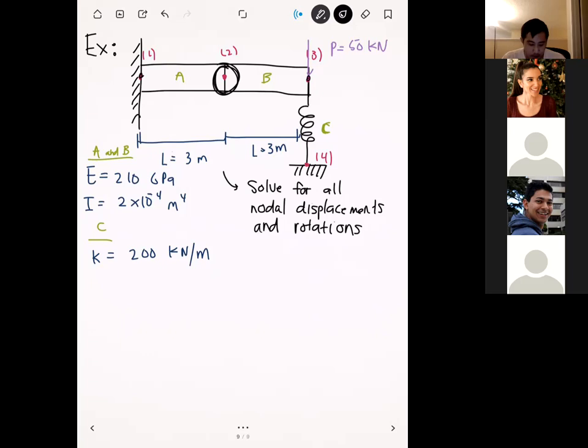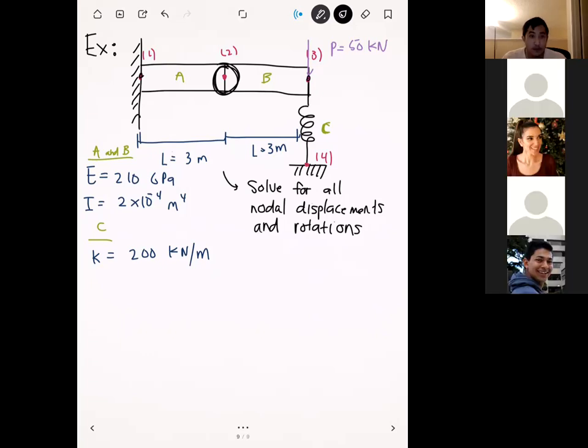Gotcha. Yeah. Thank you. If we cut both the elements in half, would that just be more accurate? Yep. Actually, that's my next point too. Cutting it just once is arbitrary, right? But if you want more spatial resolution, you can keep cutting this beam up, just like that, and you can make like a nice candy necklace or something like that. But just remember that every time you cut the beam in half, that's one more element stiffness matrix, and your global system is going to grow by that much too. And so it results in more accuracy. It just ends up being more work.